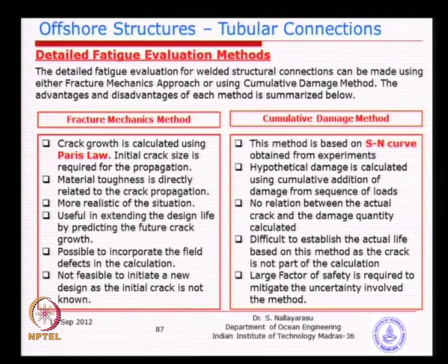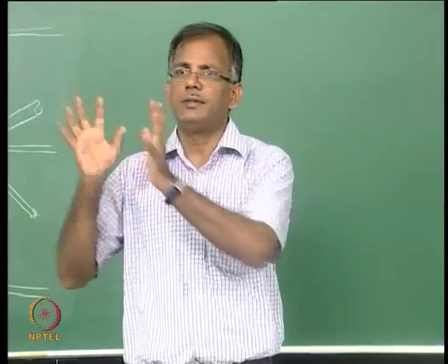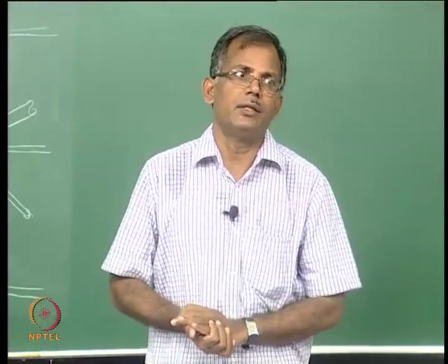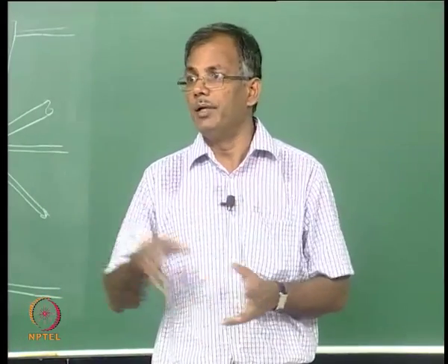And then for the detailed design methods, there are two methods distinctively we can identify, which are going to be used in real practice. Of course, the left side one, we have discussed enough, the fracture mechanics method, where we derived the formula relating the number of cycles to the crack growth from a_i to a_f. So, these two have been related, and we got a relationship defining cycles and stress range with some constant: N times S to the power m is equal to some constant.